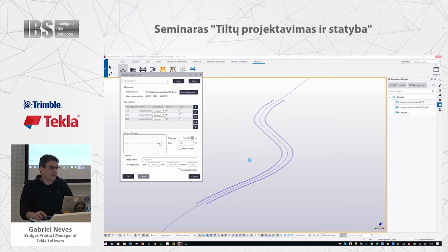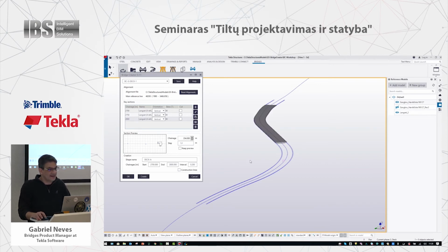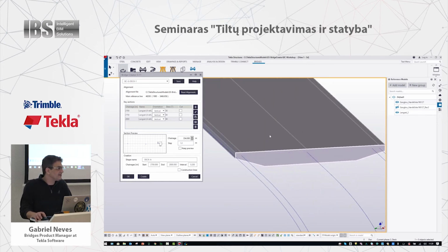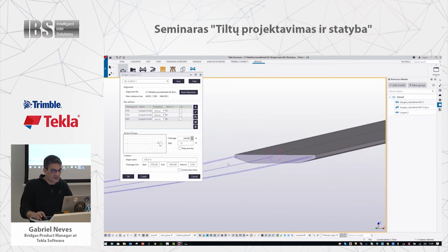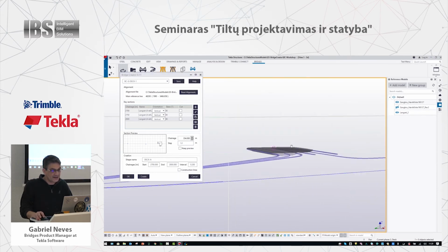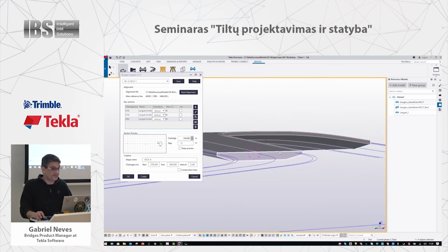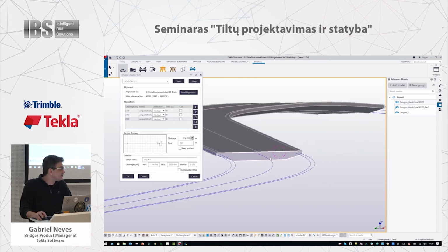But it is normal because when they design the road, they do a quick estimation for the headroom, and they always go through very narrow spacing. But they are not bridge engineers, so then they thought, oh, the deck will be 800 mil depth. That's not enough. So we need 1 meter. So then they changed the road alignment. Then we need to change everything. For us this is real because we have viaducts like that, and it's a nightmare to model, not anymore.